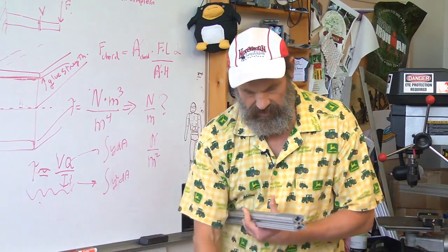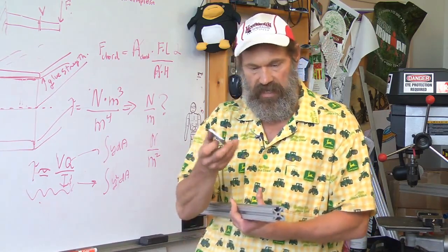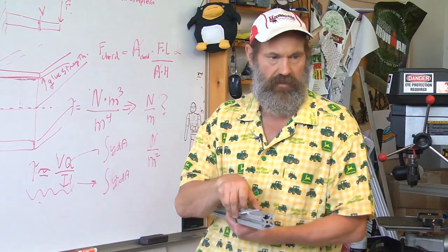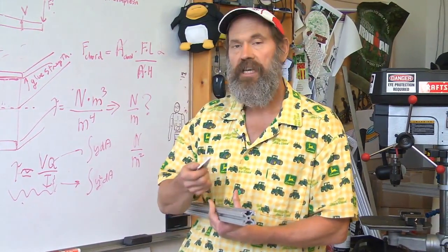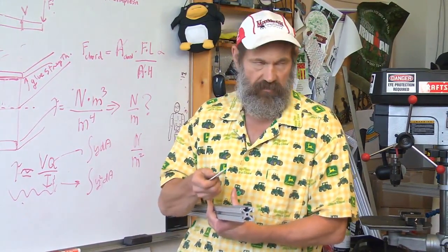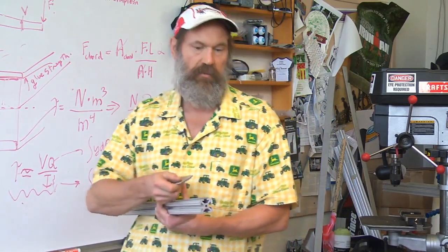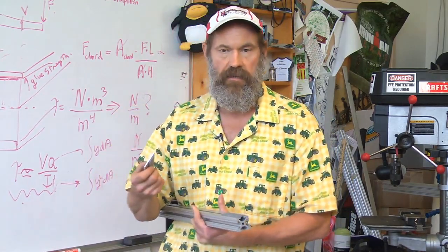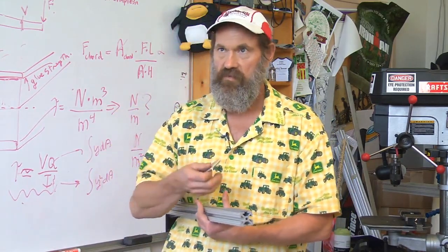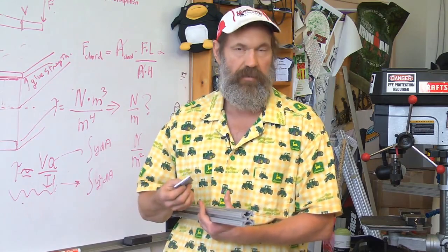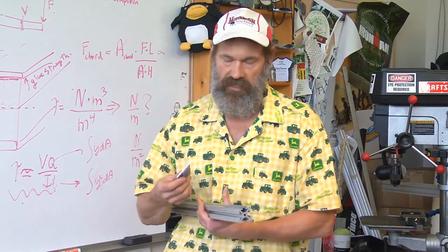And we talked about using an adhesive where you could adhere a plate, but then that's permanent. Maybe you want to be able to adhere a plate like a machine cover and make the system stiffer, but then be able to remove the cover very easily and service the inside of the machine. So we want the cover to be part of the stiffness and strength of the machine.